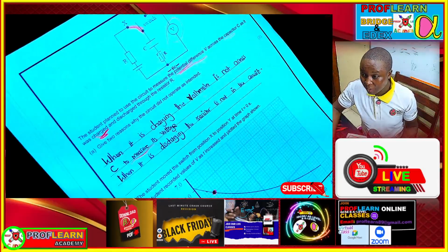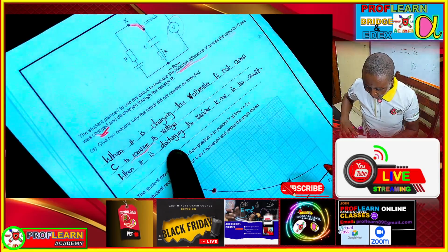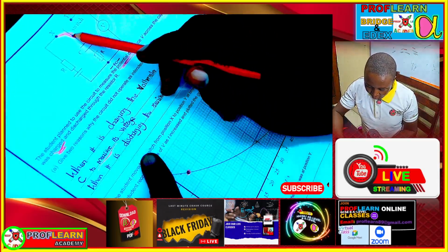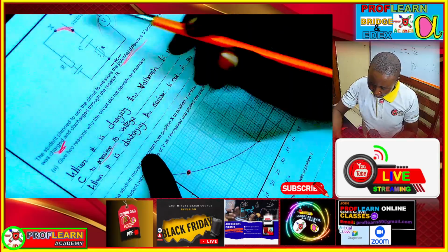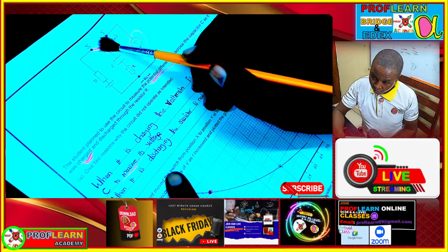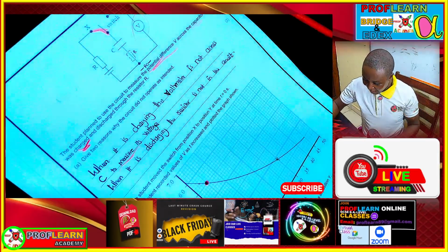And when it's discharging, when this is connected on the other end here, it means the resistor will not be in connection. So ideally, the student could have connected the resistor at this point and then connected the voltmeter somewhere here in order for it to function as intended.